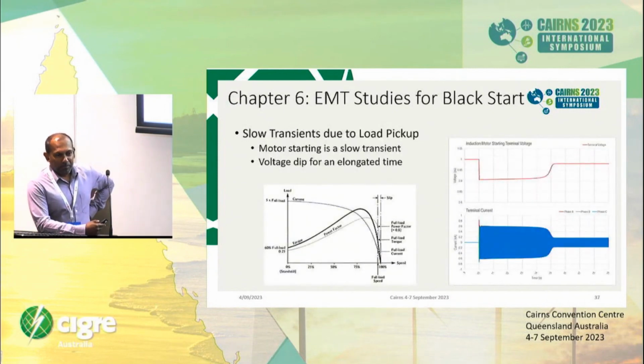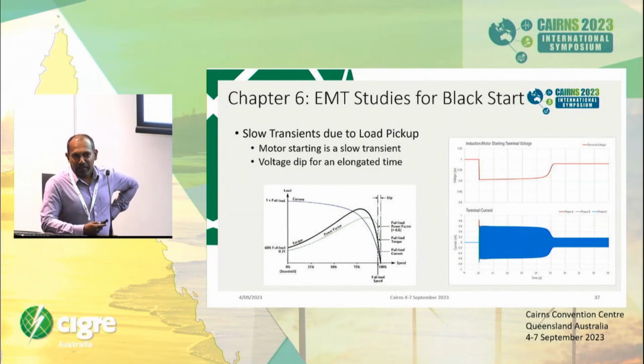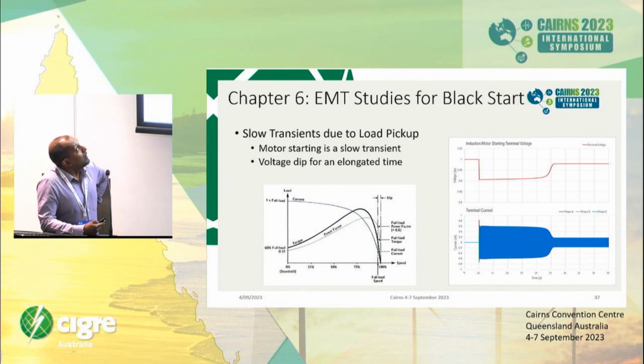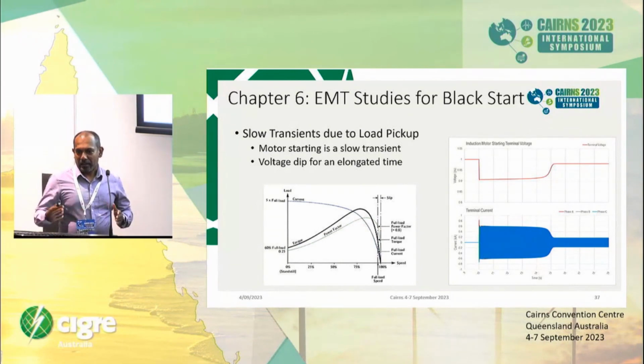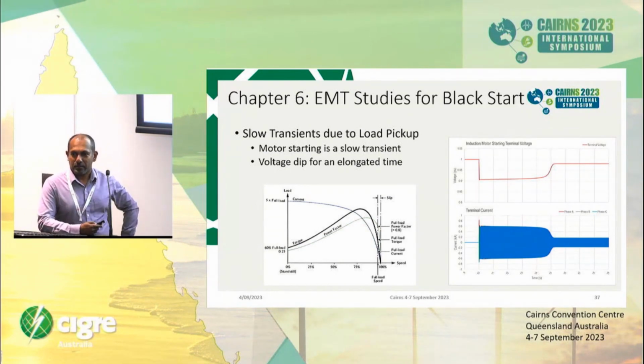The load pickups like motor start can definitely be studied in RMS or phasor domain software too, but I have highlighted that you can do it in EMT tools too. There are longer, elongated under voltage conditions, so you have to be aware that the surrounding loads won't trip due to these conditions, and that the voltage drop is within the limits.